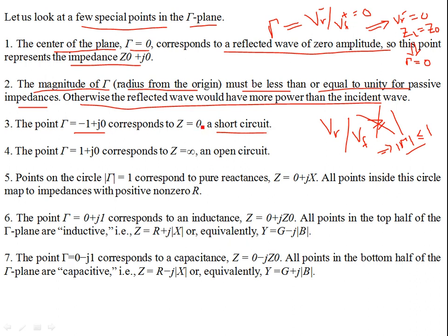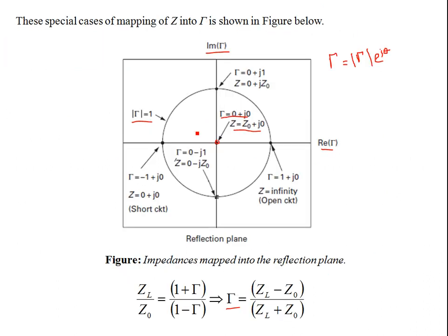Okay, you see, at Z equal to 0 in this expression, if you evaluate the expression at the ZL short circuit condition, which is 0, this comes out to be exactly minus 1. So where is the short circuit? Let's locate that. The real part is minus 1. There's no imaginary part, so we are here, and we have a short circuit here. So this point was equal to 0.